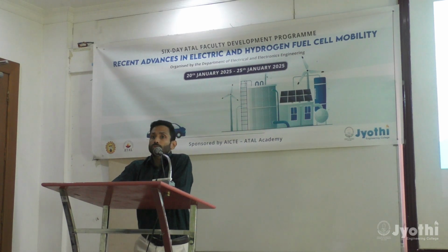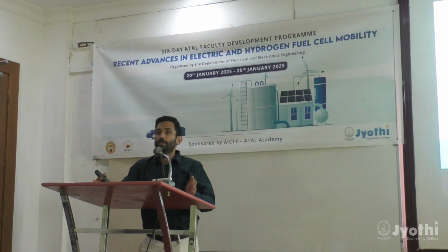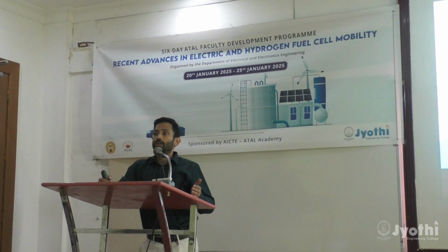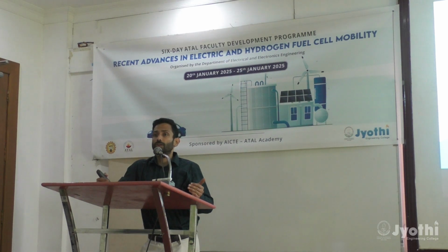But it is also highly inflammable, very difficult to store. Highly inflammable, meaning that it has a very wide flammability regime. So even if there is about 3% of air with hydrogen, then it can form a flammable mixture, and that introduces challenges in terms of the storage of hydrogen, because any small leak can create a flammable mixture, and if there is some kind of an ignition source, you could have an explosion.